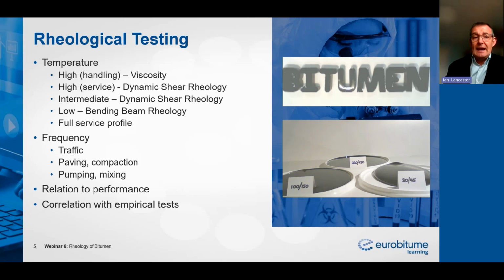So when we're looking at rheological testing at high temperature, and by high temperature, I mean handling temperatures, the temperatures at which we would move bitumen about, whether we're pumping it around a refinery or a terminal, or we're delivering it from a truck into a storage tank, or we're mixing an asphalt in an asphalt plant, or we're preparing a roofing or a waterproofing membrane.